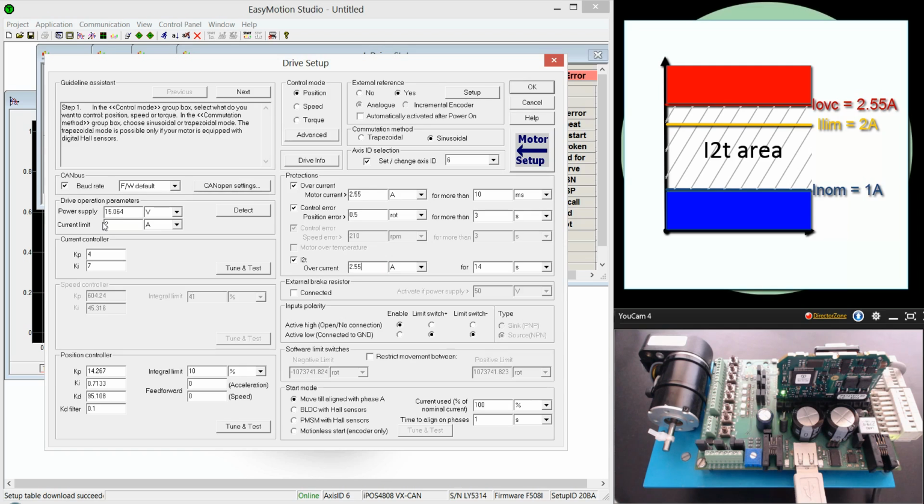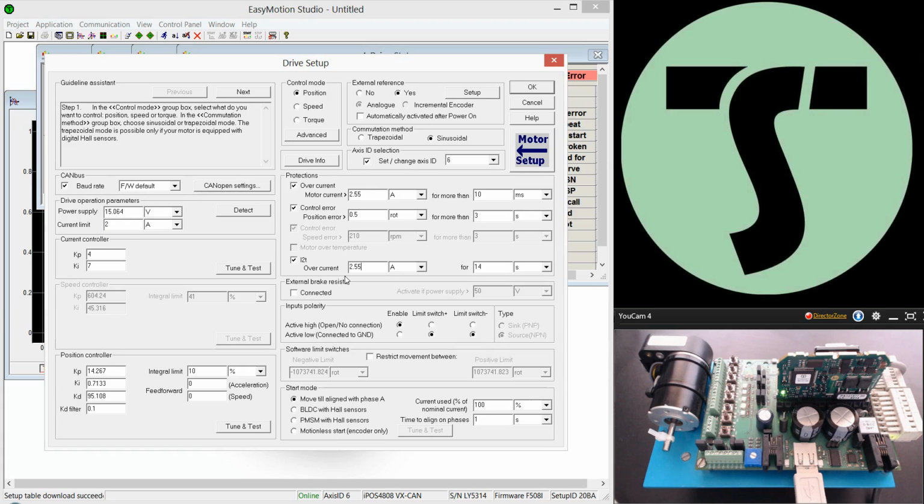The idea behind it is that when the current through the motor exceeds the nominal value, the motor will start to generate heat through current losses faster than it can dissipate it, and therefore it will start to overheat. Based on this fact, the I2T parameters are used to define the overload capacity of the motor, and that will ensure protection for the whole area above motor nominal current.